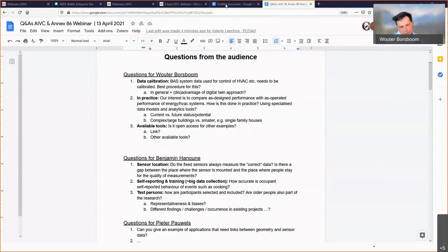Another model we use is for IAQ sensors. We had like 100 IAQ sensors, and we use the model to calculate the exposure, and also to detect which particulate matter came from outside and which comes from inside, so we can have an idea about the sources.